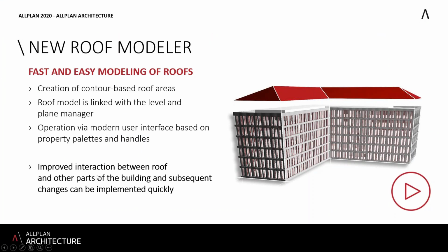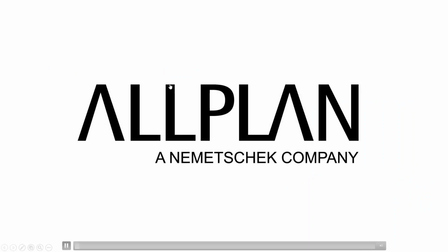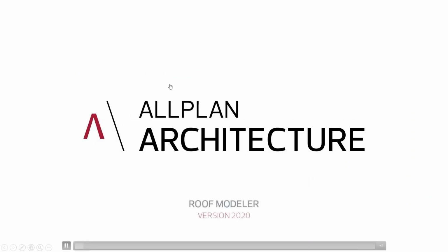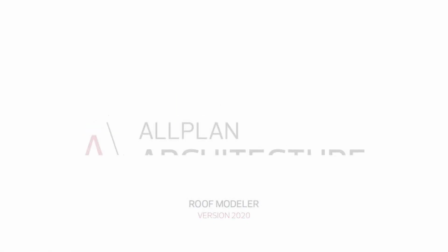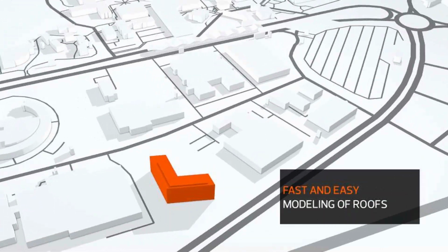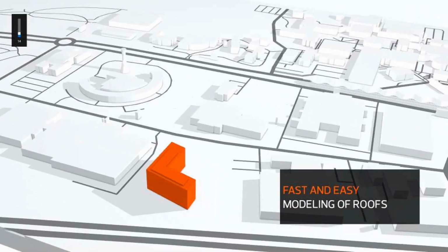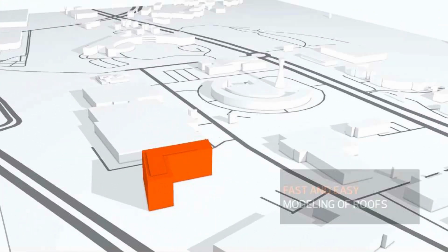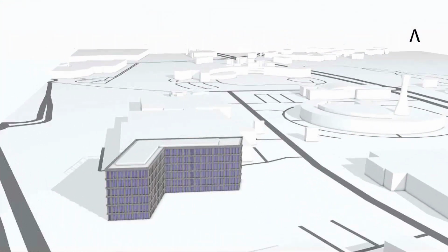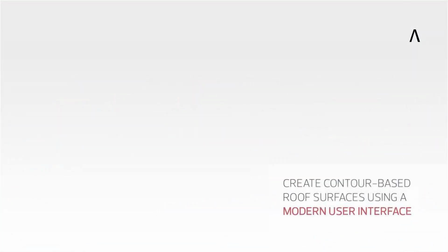There was another issue that somehow related to Allplan architecture, which was the roof. Roof sometimes was very complicated to do, especially for civil buildings. For precast, usually we rely a lot on 3D modeling, but at the same time, the advantage of having a roof structure is that elements will take slopes. So if we model the roof easily and then assign structural elements that are made with architectural functions, they will always align to those slopes and to the roof.